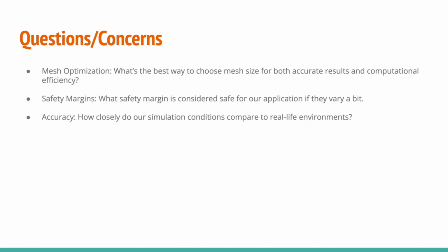On safety margins, safety factors can range from 2 to 6, depending on the potential risk involved and the unpredictability of operational loads. For example, in aerospace, factors of safety are often lower due to a need to minimize weight. Safety factors might range from 1.2 to 1.6 for different parts of the aircraft.